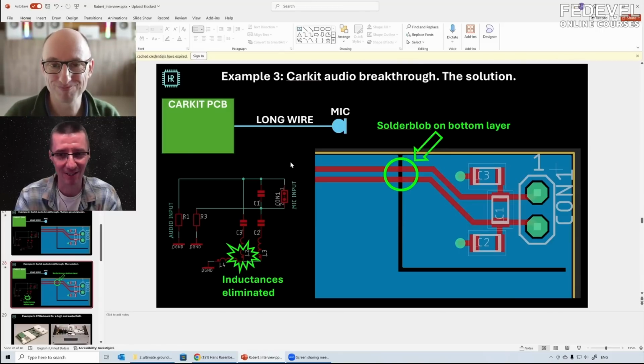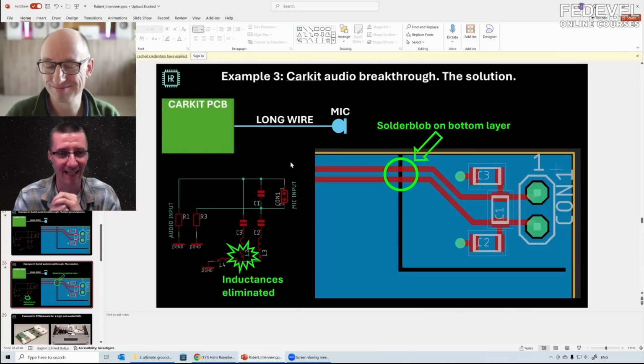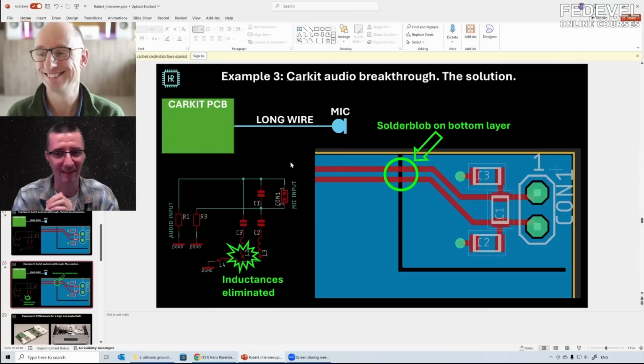And there was this senior engineer and he told me, don't do it like this because it will not work. So I was like, okay, I'm going to do an experiment. I placed footprints for 0 ohm resistors all around, and you know what happened? We measured EMC, and when it was connected only in one point through one 0 ohm resistor, it failed EMC. When we connected everything as a solid ground plane, it passed everything. Great. So yeah, this was one example.